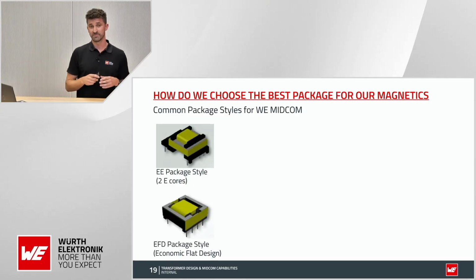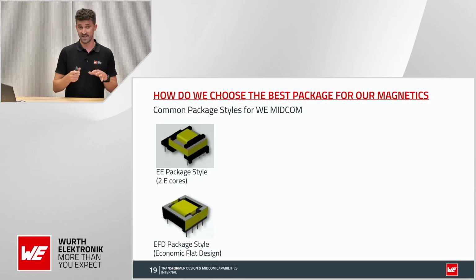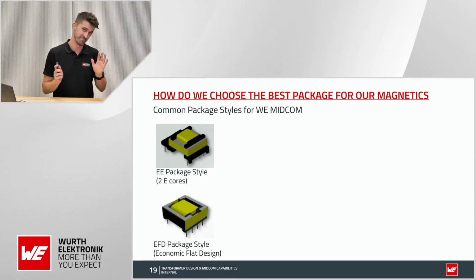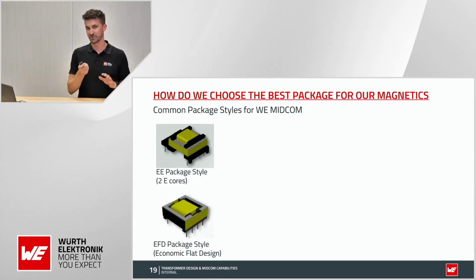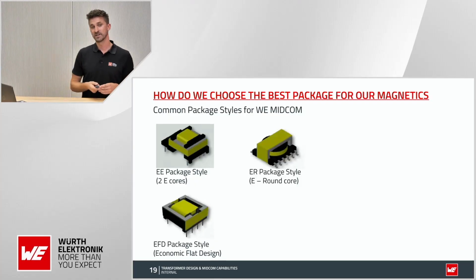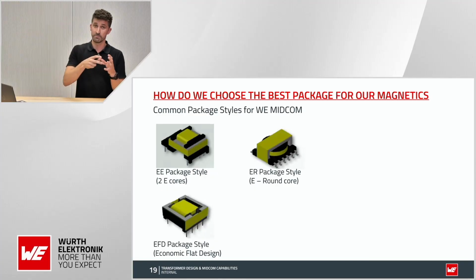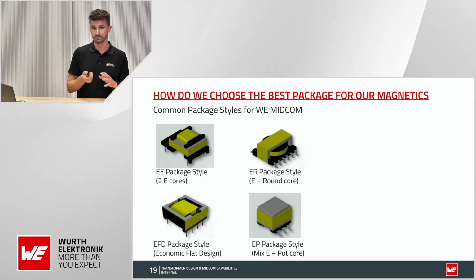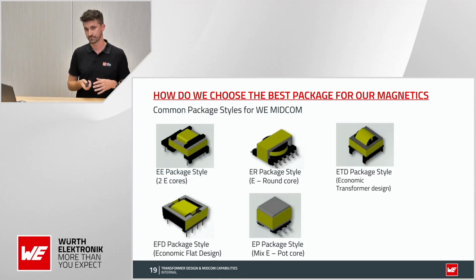So I kind of agree that it is flat, because it's a very low profile part, but economic, really, I'm not sure about it. You will tell me more later what you think about it. And then talking about low power, we can see here an ER package style, because the core is a mix between an E and a round core. This is one of our best sellers, and this is also a very small package, which is an EP package, because it's a mix between an E and a pot core.